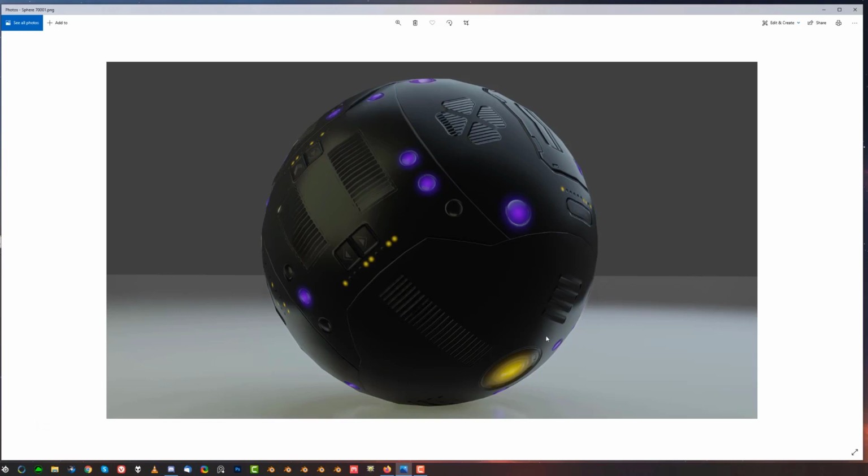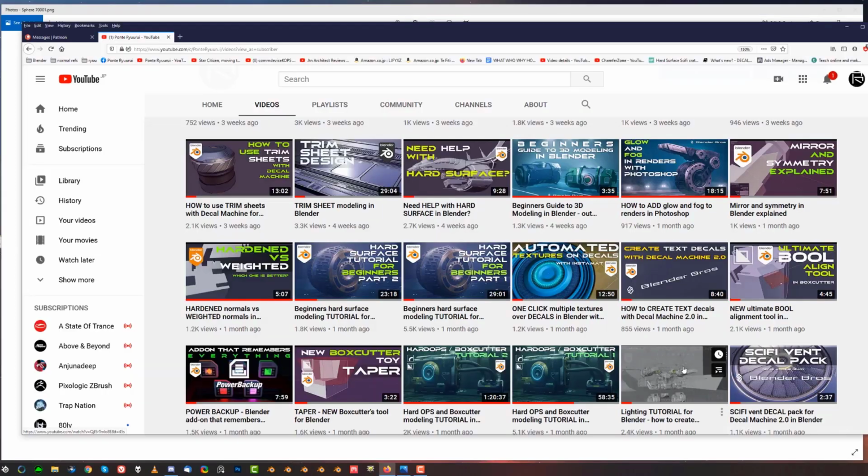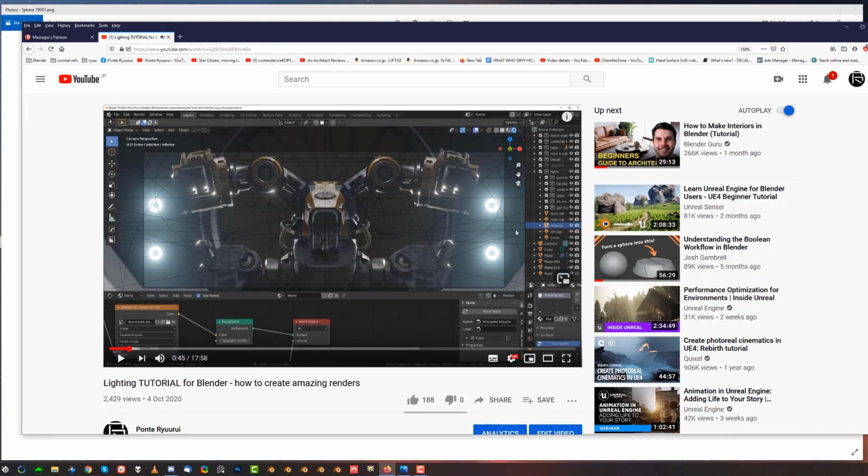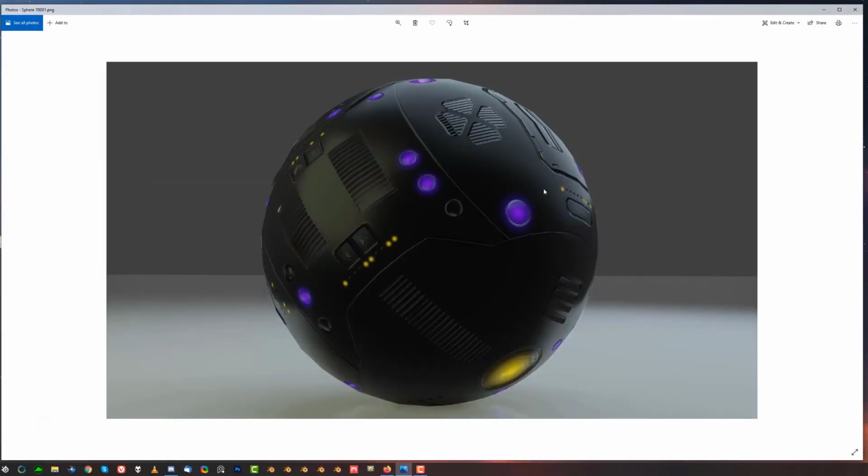If you have problems with lighting, go ahead and watch this video I dropped on YouTube: a lighting tutorial for Blender and how to create amazing renders. In this video I discuss lighting and how I set them up. It's a complicated light setup, and you'll understand how to set the lights and how to give them a purpose, because it's really important.